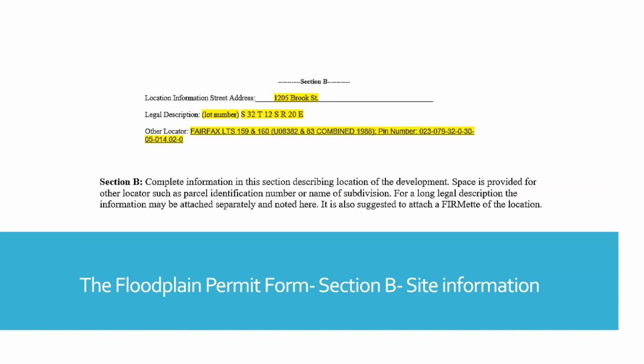I was able to put in the public land surveying system information from the National Flood Hazard Layer, which I'll show you. So I was able to get the section, township, and range, and I wasn't able to find the lot number. But I got at least that much, and if I was really building this house, I would have access to that information. And then I was able to find this tax parcel information from a Douglas County property search site. So your community might have something like that that will help you to verify this kind of information.